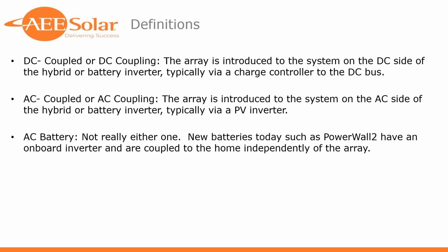To further complicate the issue, though, in the past couple of years, we've seen a number of, I call them AC batteries, that have been introduced. So these are standalone batteries. I would say obviously, but I don't think that's the case. There are no battery chemistries which store watt hours in an AC fashion. Every type of chemical storage is by definition direct current. The difference occurs when inside that box that you're ordering from Tesla or someone else, there's an onboard inverter, so that when you connect it, the output of that device is already AC.